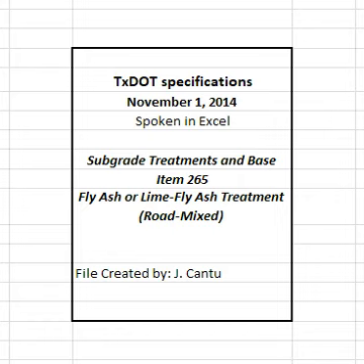3.1 Storage facility. Store quick lime, dry hydrated lime, and FA in enclosed, weatherproof containers. 3.2 Slurry equipment. Use slurry tanks equipped with agitation devices to slurry hydrated lime or quick lime on the project or other approved location. The engineer may approve other slurrying methods. Provide a pump for agitating the slurry when the distributor truck is not equipped with an agitator. Equip the distributor truck with a sampling device in accordance with TEX 600J, Part I, when using commercial lime slurry.